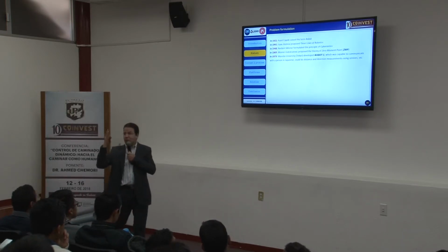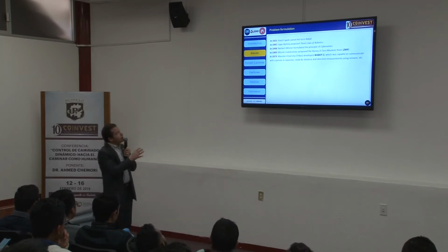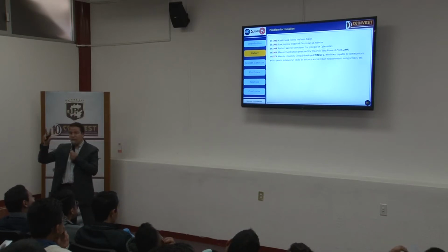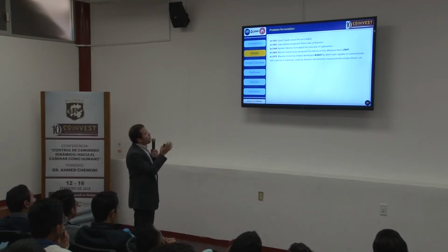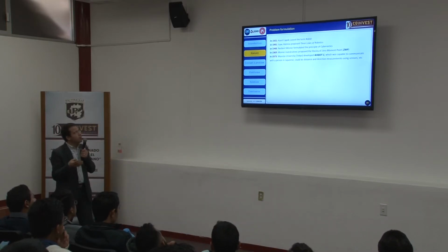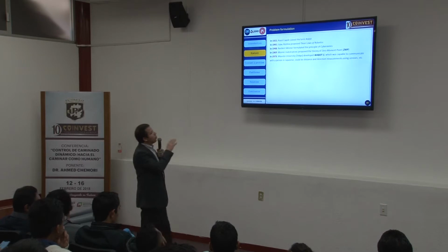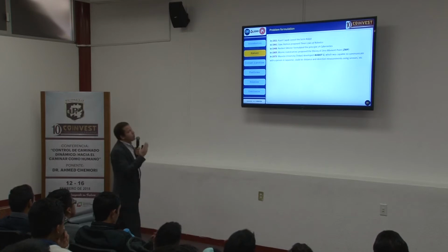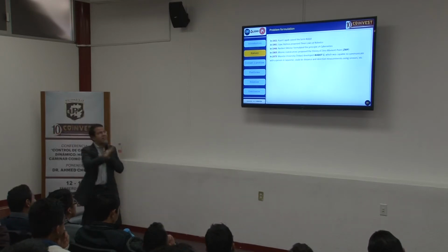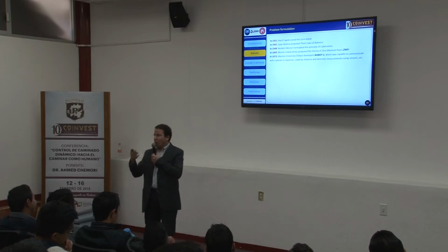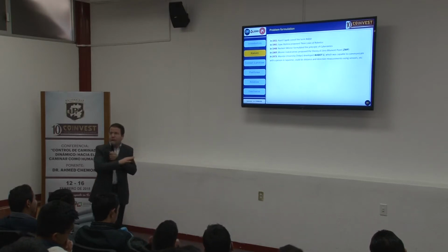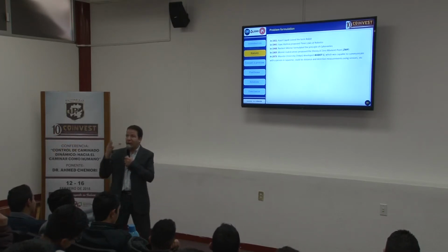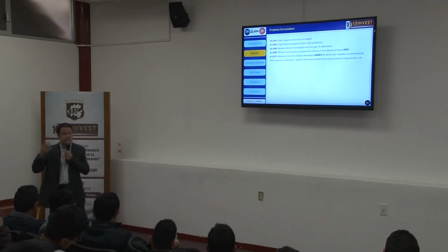So the term robots was first coined in 1921. In 1941, Asimov introduced the three laws of robotics. In 1948, the works of Wiener, for instance, in cybernetics. In 1969, the work of Vukobratovic concerning humanoid walking, concerning the stability of walking. He introduced a very interesting concept called the ZMP, the zero moment point. I will introduce it later on. It's a very important concept in humanoid robotics, since using this concept you can prove or guarantee the stability of the walking of the humanoid robot.